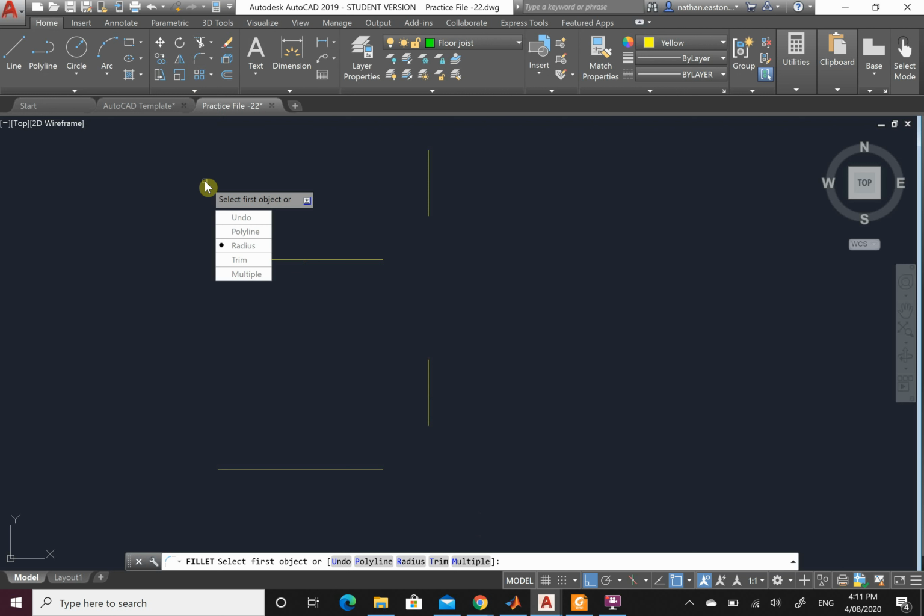What I'm going to specify is the radius. So specifying a radius, I've used this file before, so yours should be 0 minus 25. What I'm going to do is specify how much I want that line to bend when they meet. I'm going to put 300 just to show what's happening. Obviously it will be a lot smaller, you just have to zoom in to see it.